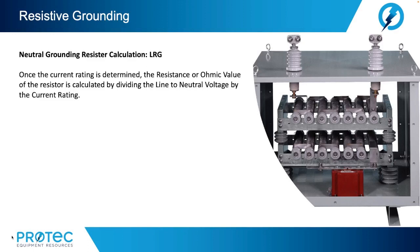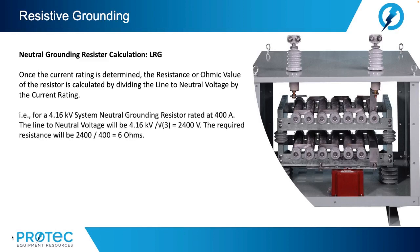Once the current rating is determined, the resistance or ohmic value of the resistor is calculated by dividing the line to neutral voltage by the current rating. For example, a 4.16 kV system neutral grounding resistor rated at 400 amps. The line to neutral voltage will be 4.16 kV divided by the square root of 3, which equals 2,400 volts. The required resistance will be 2400 divided by 400, or 6 ohms of resistance.